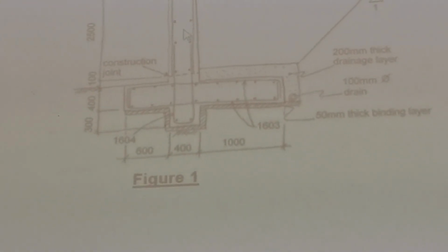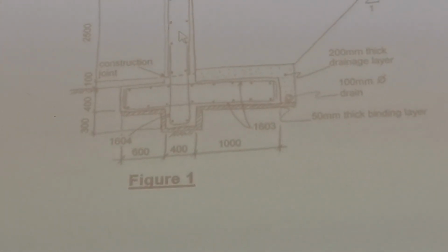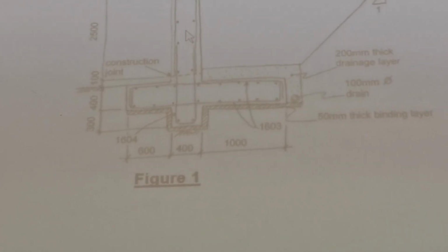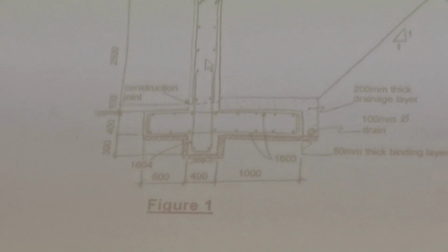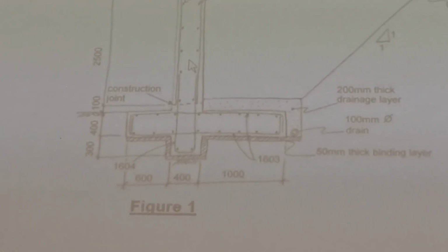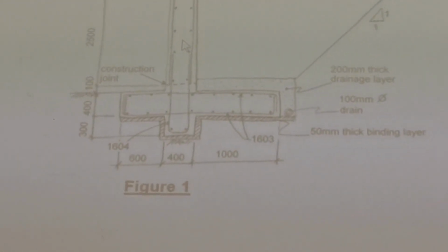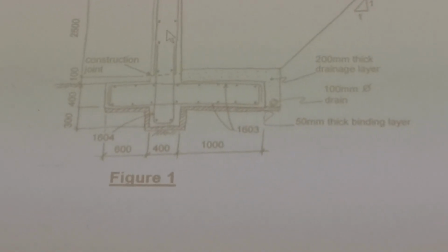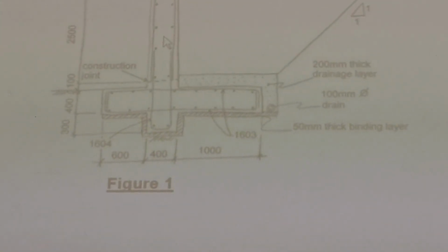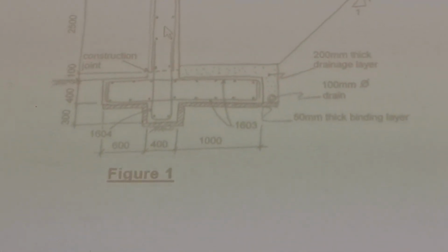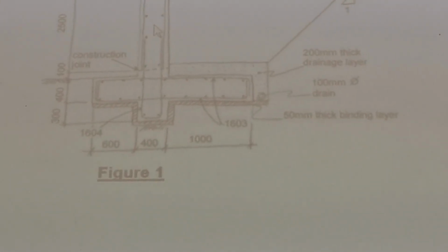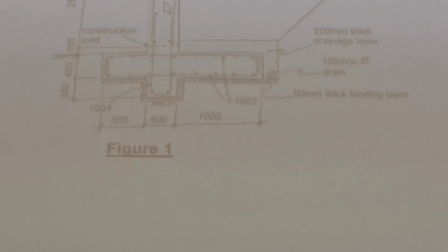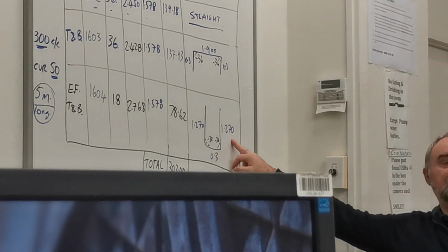Okay. So the lap, because it laps with the other one that goes up, the lap on the table at the top up there is 520, plus the next dimension's 100, the next dimension's 400, but the last dimension's 300 minus the cover of 50, right? So that makes that one. It's repeated on the other side.